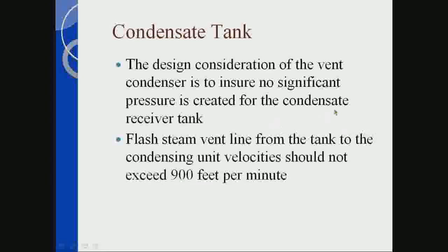We got another one here, too. They're asking what's the minimum flash steam pressure required to use thermal compressing? Wow. It depends on motive steam and things like that. 10 PSI. It's not an easy answer. It's really a lot of balancing and everything else. I have done 1 PSI. It's very difficult. We've even done work on half a PSI, which is also difficult. But it just depends on the system. It has to be designed for the system. So, great questions.